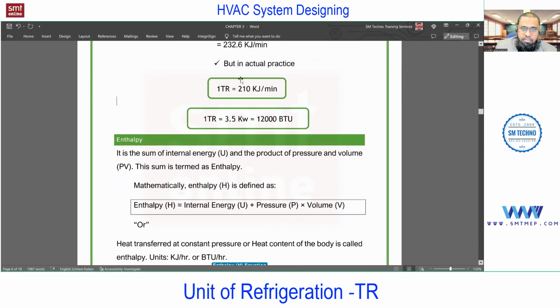For a 1 tonnage machine, how much electrical capacity is required? 0.8 to 1.5 in between. That depends on the efficiency. But don't write that down. We'll discuss this at the time of machine selection. Or from an interview point of view, you can consider 1.2 to 1.4 if you talk about split.